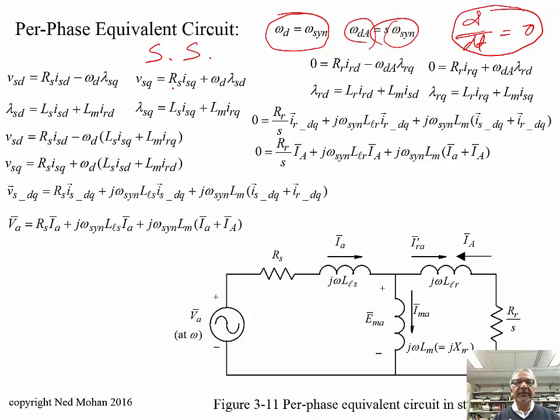Whereas when we go to this dq analysis, first of all, we have 2 sets of windings, and each one has only 2. So the q-axis winding is decoupled from the d-axis winding. So that's the beauty of this dq-axis analysis. So we can write all the voltage equations here like this, also for the rotor circuit here.